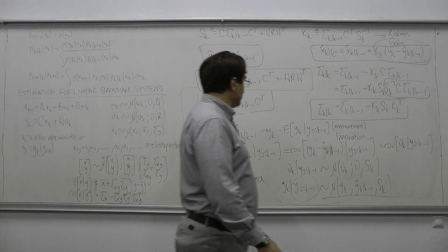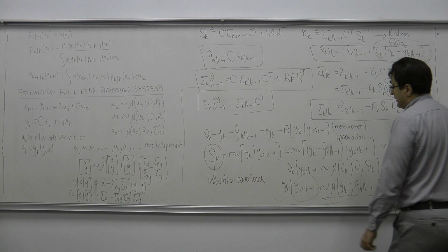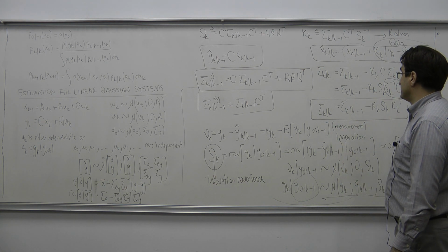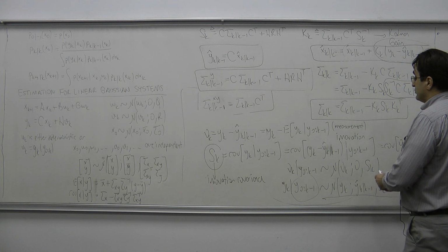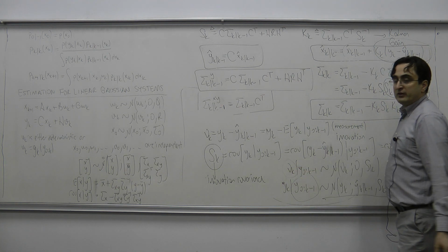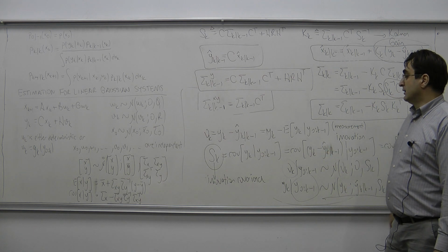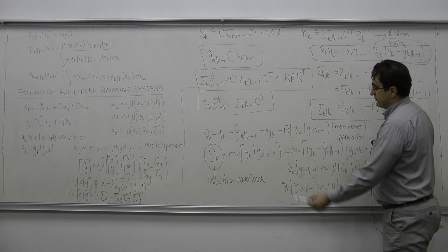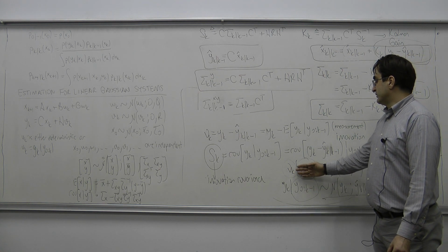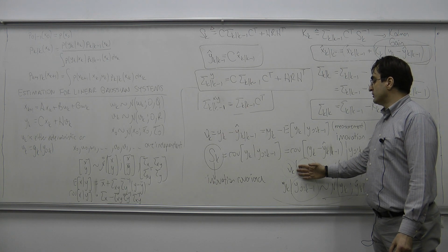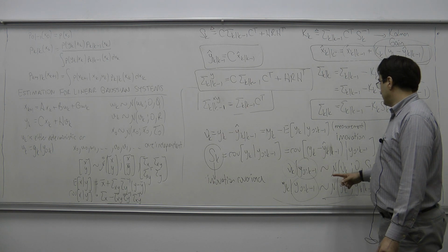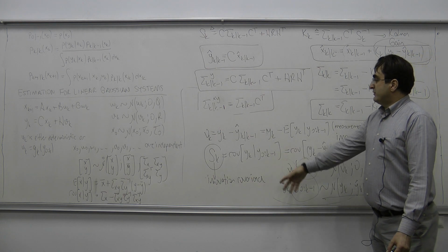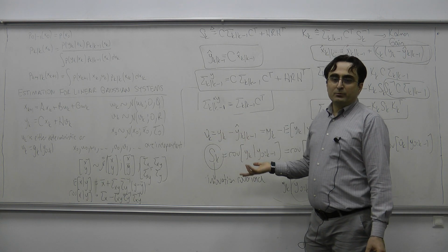Actually, when we look at the properties of the Kalman filter, we're going to see that the innovation process, nu k, is going to be an independent process. Okay? So these given conditions won't mean anything. So the unconditional distribution of the innovation is just going to be this one. Actually, we know that yk is a Gaussian process.